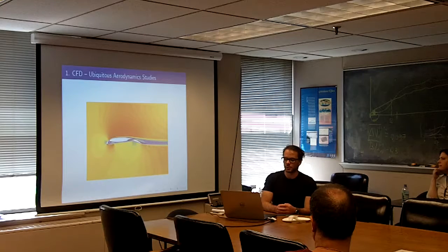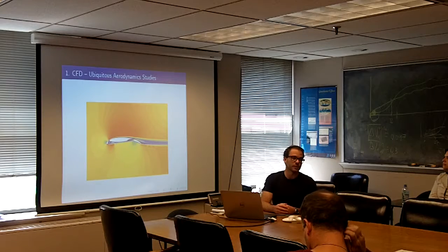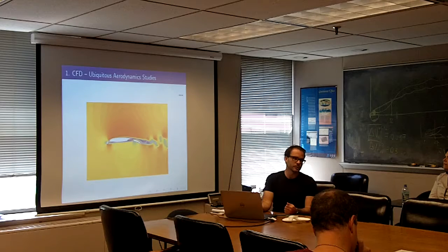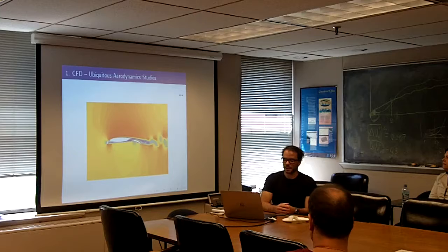Okay, so just as an example of what I'm talking about, this is the ubiquitous aerodynamics example, solving for the flow over an airfoil section. So what you would do in an industrial problem is you need to impose all of the no-slip boundary conditions. So even though the boundary layers are incredibly thin at the top and the bottom surfaces of the airfoil, you need to locally increase the resolution of the mesh there so that you can accurately resolve that boundary layer. You also need to use enough resolution in the regions where interesting things are going on, so in the wake region, for instance, so that you can resolve enough of the spectrum of the eddy field, essentially. So unless you have massively powerful supercomputers, you still would use some sort of lower level turbulence closure, but typically there's an effort to capture a lot more of the eddy spectrum.